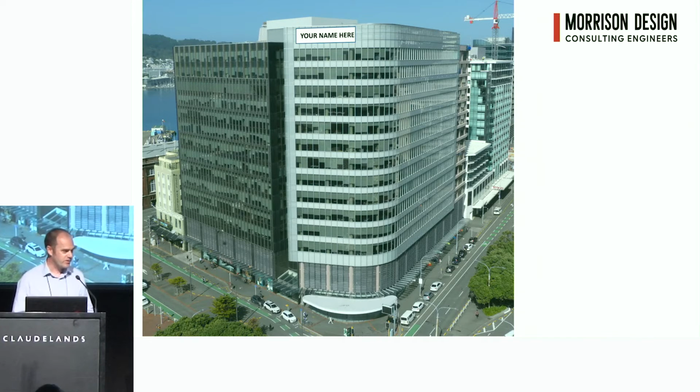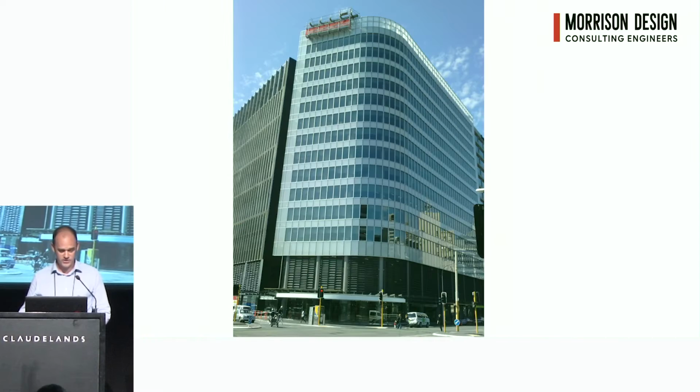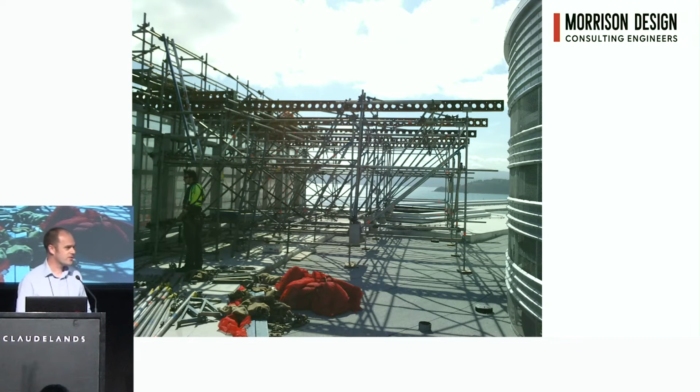For this particular building, we had a couple of options. Ideally, we would have started at the ground and built a scaffold up, and then they would have done the signage that way. But you can see there's a fairly large canopy down at bottom level, which prevented that. So our other option was to cantilever off the roof and put the signage in that way. You can see that this is quite an undertaking to do these cantilever scaffolds.